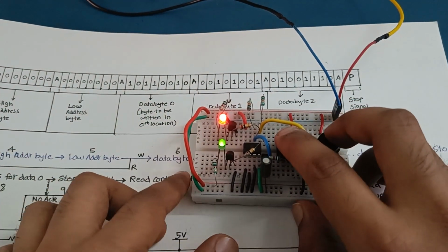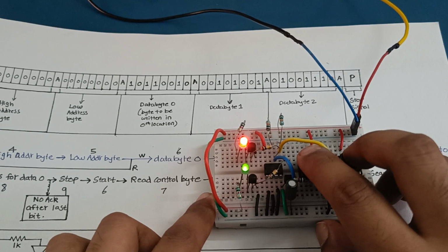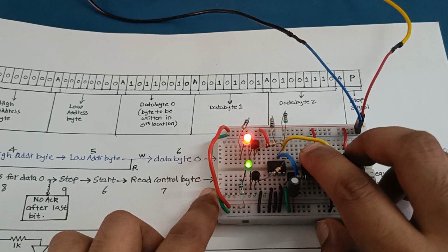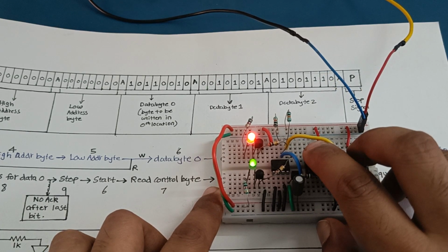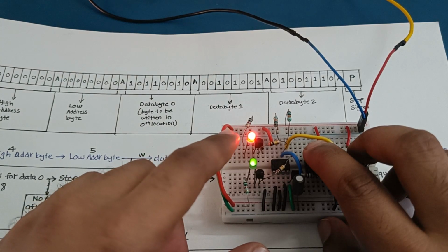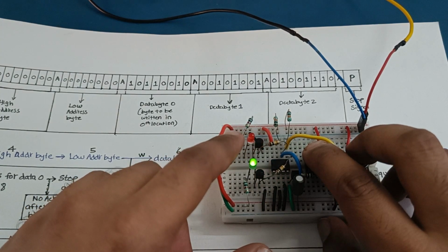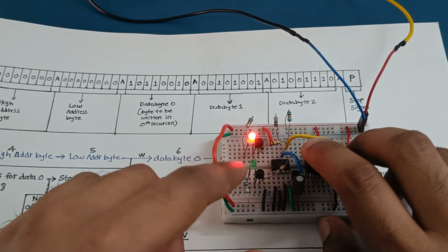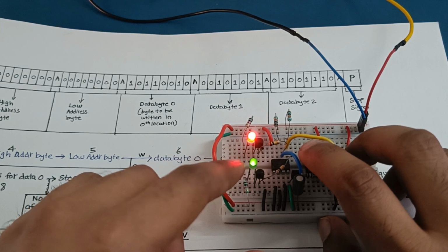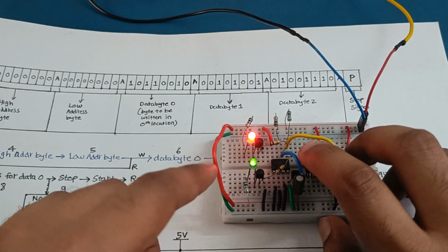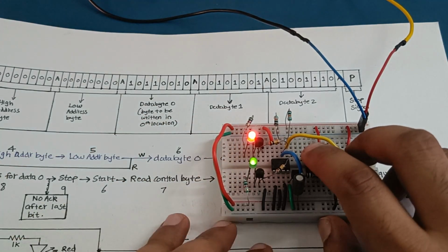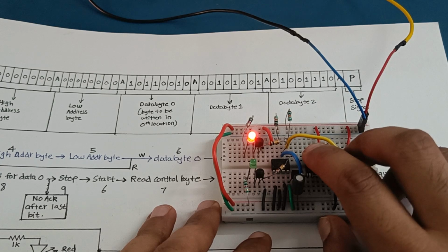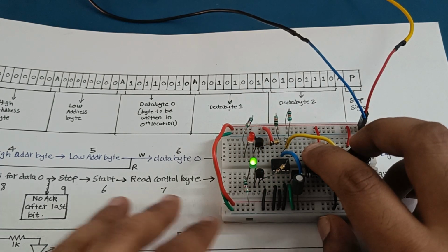So now again I have to send a stop command. So that I will send by, first I have to pull the clock line low, then the data line low, clock in a 0, then pull the data line again high, so that gives a low to high pulse when the clock line is high. It's a stop command. And again we have to generate a start command and then send the read control byte,